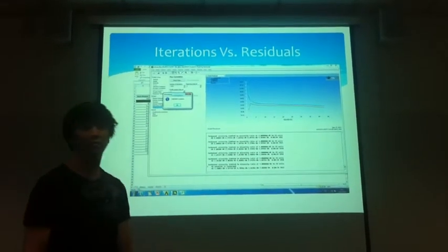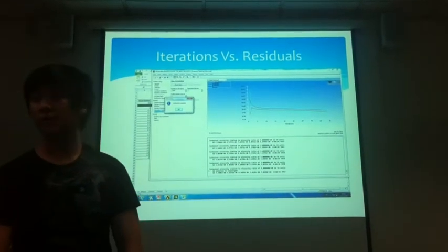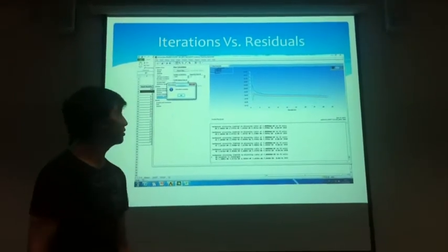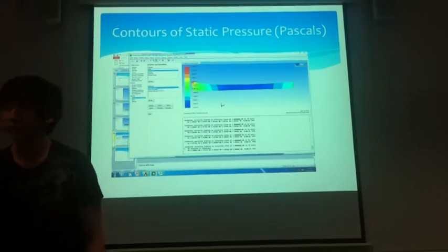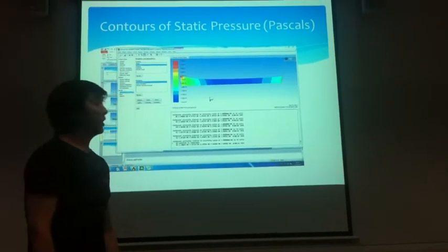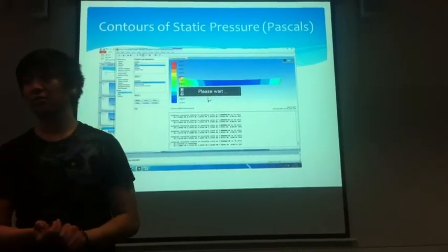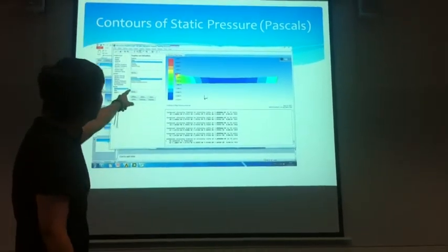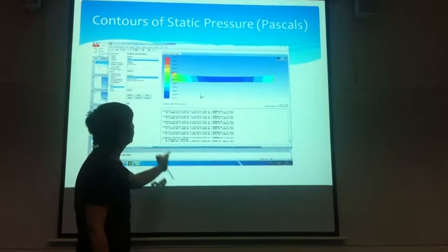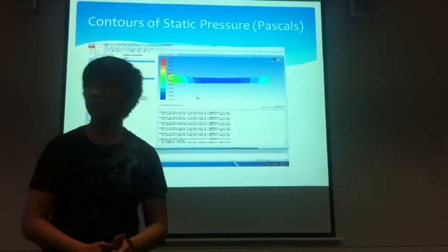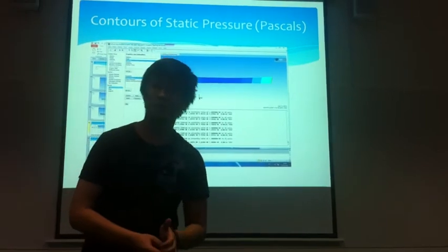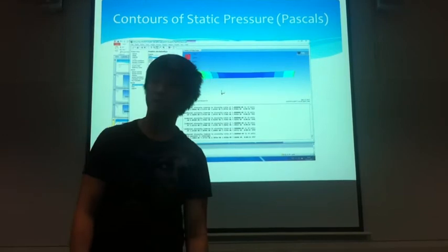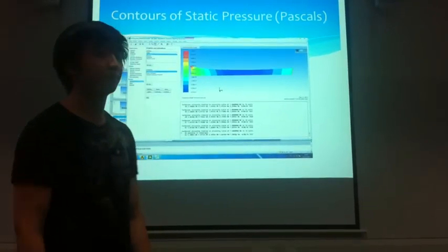These are my initial results that I created using my consistent mesh, showing the residuals of the first iterations. And also from this, I was able to show the contour of pressure. As you can see, the top left of the mesh has a red point on it, which is where all the pressure is from. This is due to sudden directional change of the flow. To fix this, I have to make the start of the nozzle perpendicular to the pressure inlet.